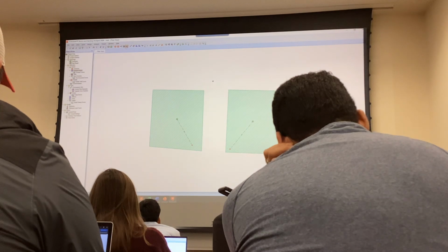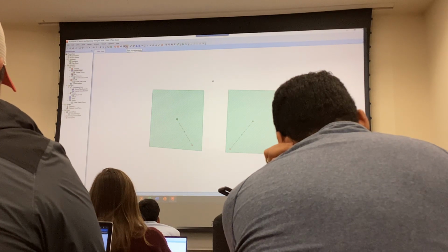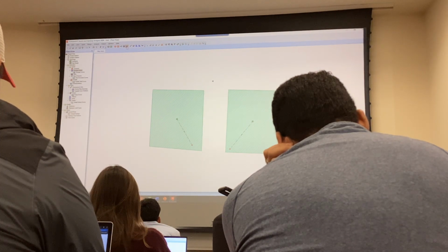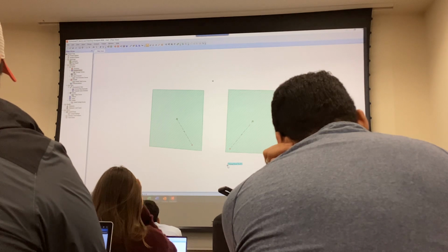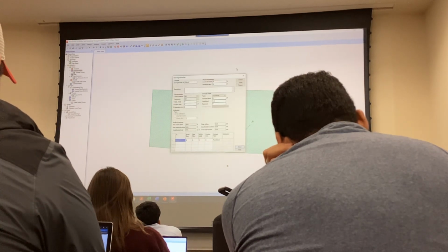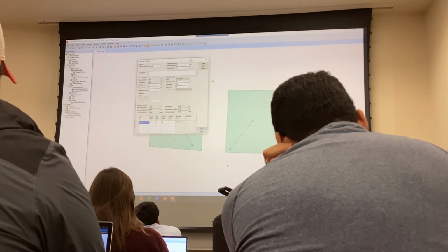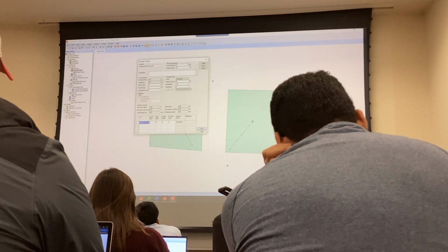It shows a tank. It's like a cup, okay? It's storage, okay? So you can just click on over here and say that this is now my storage node. This is my detention basin. Okay? So you click on here and you can specify what goes in your detention basin and where you're going to put the water out from your detention basin.